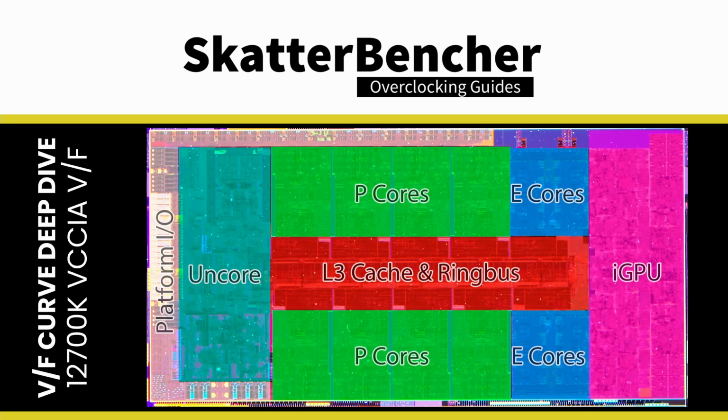For the 12700K, there are a total of 10 relevant VF curves for our VCC-IA voltage rail, 1 for each of the 8 P-cores, 1 for the E-core cluster of 4 cores, and 1 for the ring. So how does the CPU decide which voltage to set? Actually, that's pretty straightforward. The VCC-IA voltage is the highest among all the requested voltages.